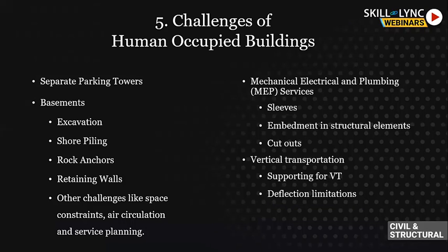As you go down, the water pressure increases, and the bottom slab will require rock anchors because of the water pressure, it might just uplift. Another challenge of the basement is again the retaining wall, because there is a huge lateral pressure coming up because of the soil retention and also the water pressure. Some of the major damages that you see in the videos during the rainy days is the damage of the retaining walls. So again, a structural engineer is called upon once these sort of things happen.